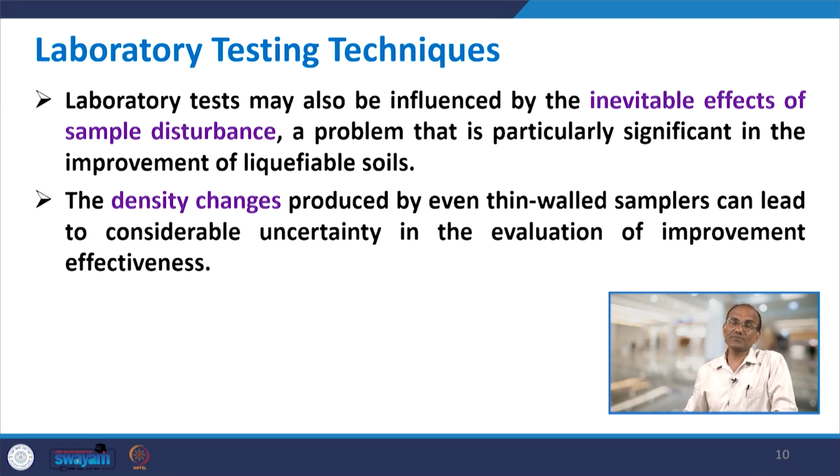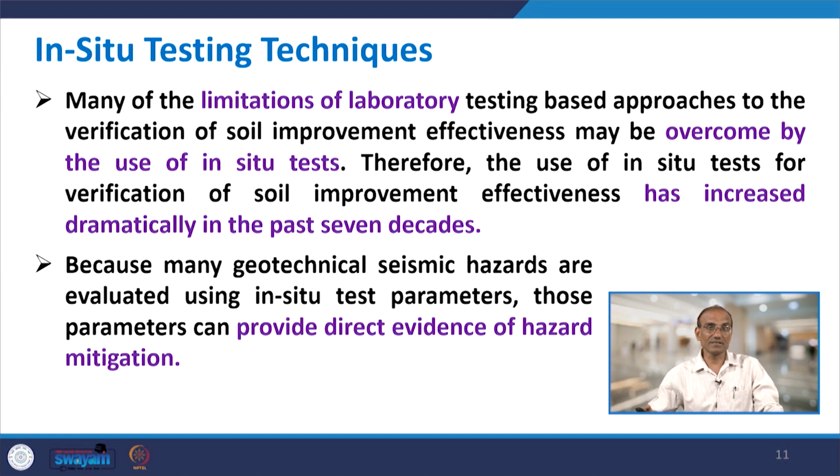Laboratory tests may also be influenced by the inevitable effects of sample disturbance, a problem that is particularly significant in the improvement of liquefiable soils. So, the density changes produced by even thin walled samples can lead to considerable uncertainty in the evaluation of improvement effectiveness. What you want to judge in the lab is whether the conditions which you have in the field are effective or not. In that case, the first thing is how well the sample which you are testing in the laboratory represents the field conditions. So, that is also the issue.